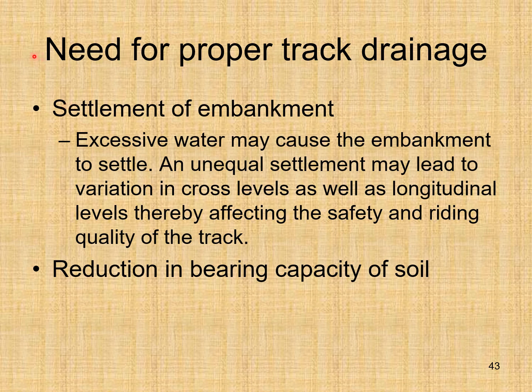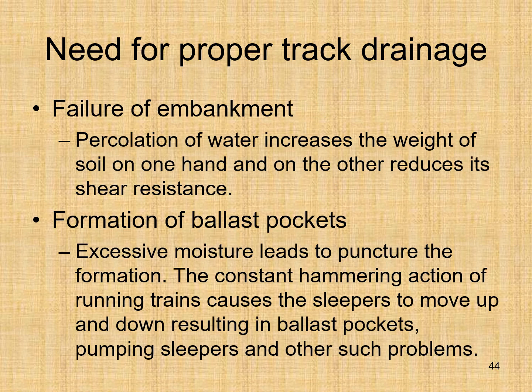Need for proper track drainage. Settlement of embankment. Excessive water may cause the embankment to settle, and unequal settlement may lead to variation in cross levels as well as longitudinal levels, thereby affecting the safety and riding quality of the track. Reduction in bearing capacity of soil. Failure of embankment. Percolation of water increases the weight of soil on one hand and on the other reduces shear resistance.